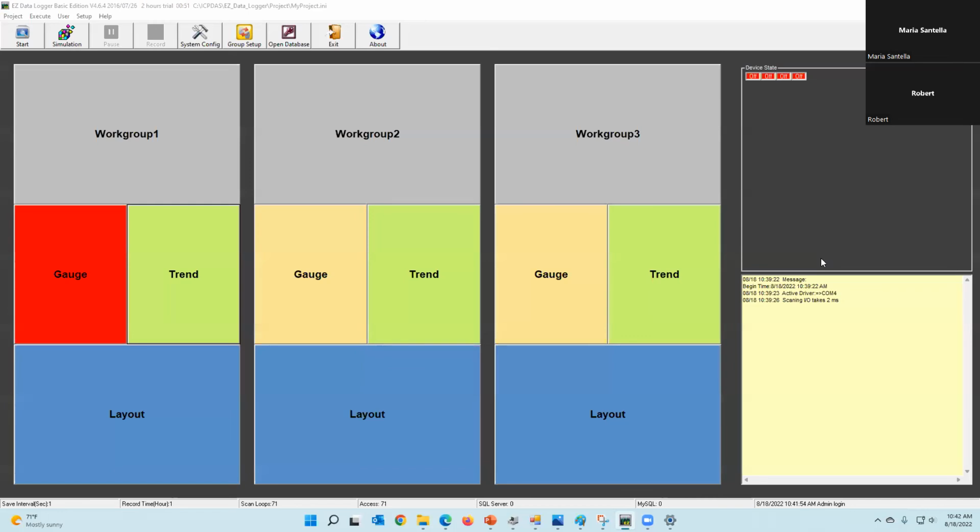Yeah, you need logic. Maybe WISE 5800 and then M-7015 and M-7060. You can use those 3 parts together and configure it through a web page. Or even our TMR5 too, but we need some more information. You say signal conditioner, but I'm not sure at what condition it's going to trigger the relay output. And how many relay outputs? This says activate a relay contact, but my assumption would be you just want an alarm condition if maybe an RTD temperature goes above a limit.